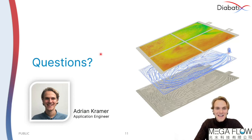Yes, of course, that is a pretty big concern. In the end of the day, it's nice to have all these shapes and structures, but can they actually be mass manufactured? The answer is actually quite simple. If your user input for the manufacturing constraints for that design region that I showed you is true to what your manufacturing supplier can do with their machining and tooling, then our structures can guarantee that they're compliant with them. So with good user input, we can deliver fully manufacturable parts for sheet metal forming or even for roll bonded cold plates.